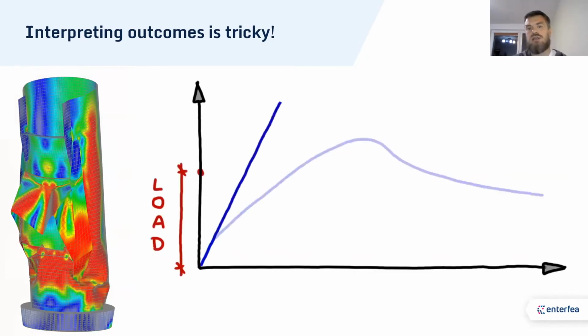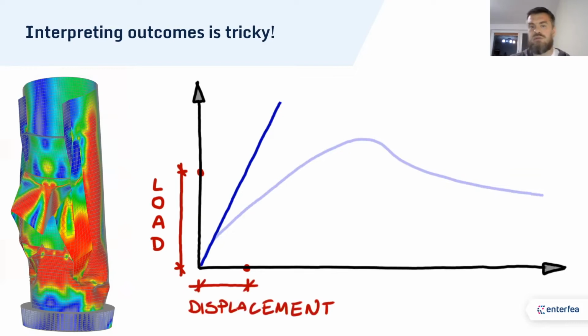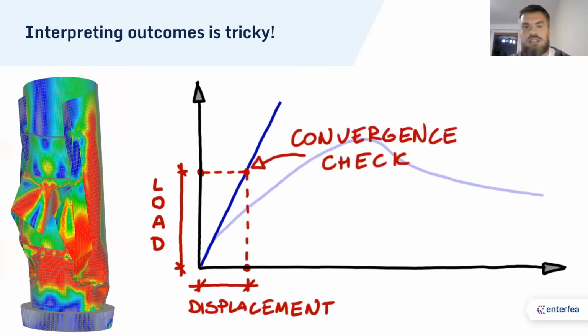Firstly, when FEA works, you apply load in certain increments. And note that, of course, the solver will assume that everything is linear, because this is how it's trained to do, right? So you apply the load, it will calculate the displacement and try to see if the internal and external work is in equilibrium.